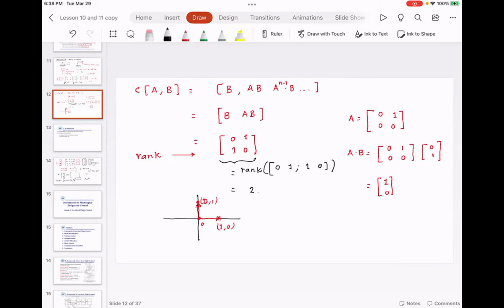What does that mean in physical form? This quadcopter has 6 degrees of freedom. There are 4 props, so you can only control 4 states. In other words, this quadcopter, just by changing the speeds, cannot go forward or sideways. So what you do is you deliberately tilt the quadcopter. That means you induce a coupling with the forward state, the X state, and then have that quadcopter go forward.